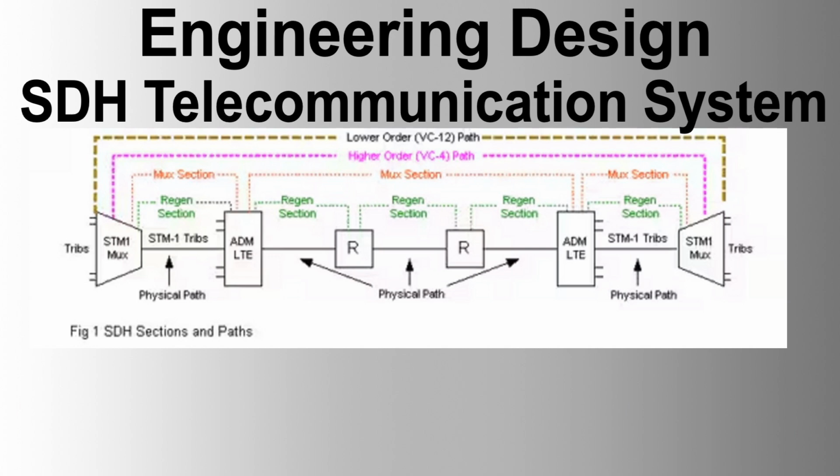Accessibility. Access levels. The SDH equipment shall allow various levels of access to multiplexers, with the highest level allowing control and testing, and lower levels confined to monitoring and collecting statistics. Protection features. 1+1 protection. Equipment shall have 1+1 protection on the line aggregates and N+1 protection capability for common control cards. Key alarm indications shall be externally hardwired for connection to SCADA RTU for alarm display.